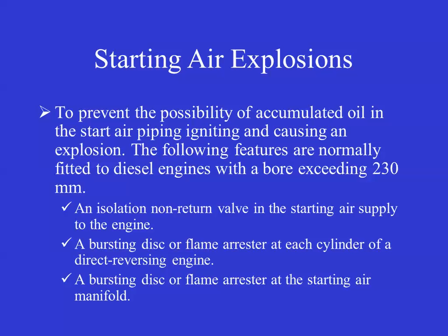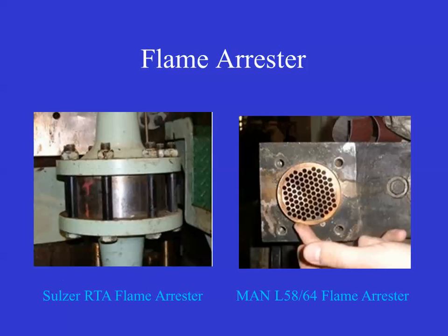So again, starting air explosions can happen on engines, and you will typically have a non-return valve in the start air system, a bursting disc, and a flame arrestor at each cylinder, and these are to help prevent that type of accident.